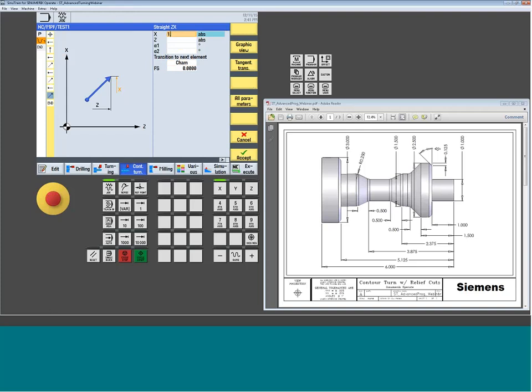We'll come out. We're coming out to 1.5 inches. I'm going back, again my 1/2. And we're coming to a radius of 1/4 inch. Straight back, it's going to get us to the back shoulder at 5 1/8.